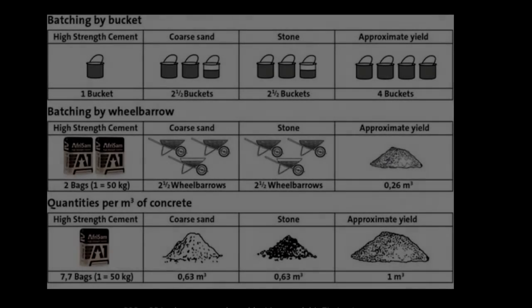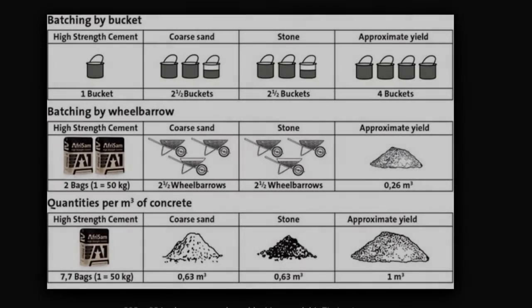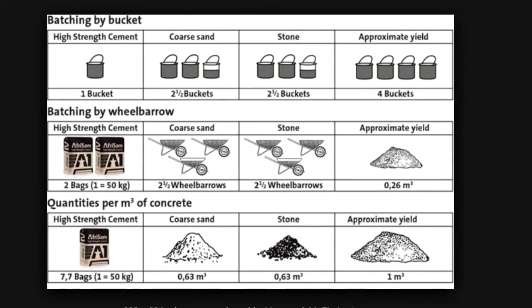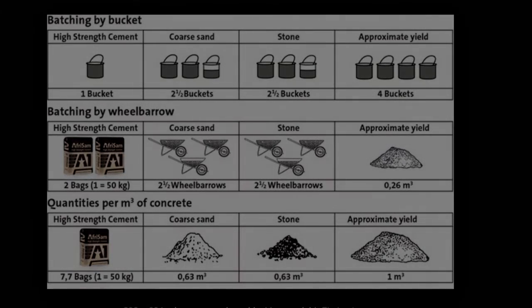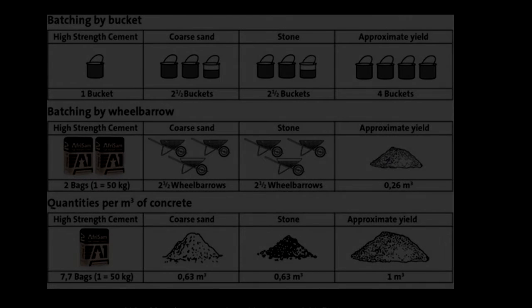Step 4 is the selection of water-cement ratio. The choice depends on strength requirement, durability, workability, and finishability. Step 5 is required cement content, which can be obtained by dividing the volume of water by the water-cement ratio. Step 6 is the quantity of coarse aggregate, which is estimated in terms of percentage of coarse aggregate inside a well-compacted concrete mix.